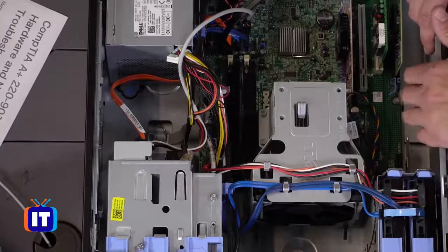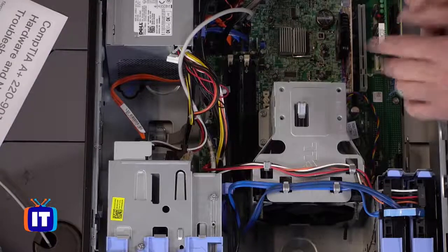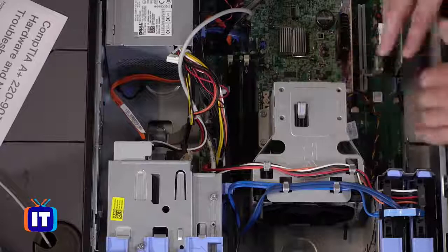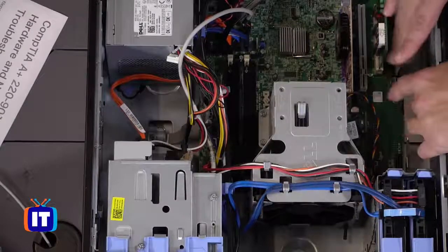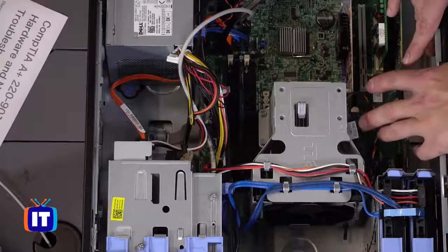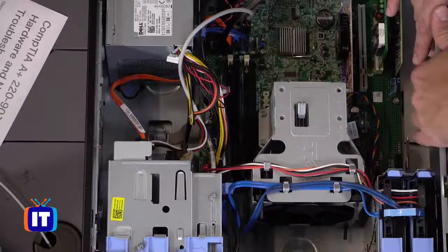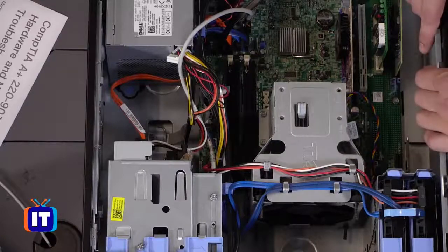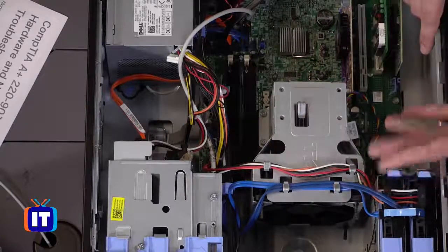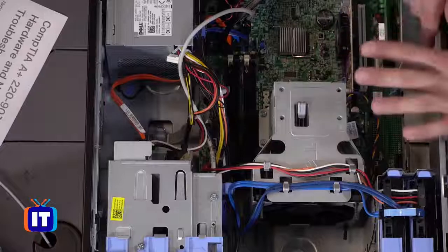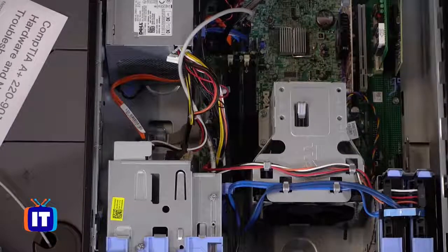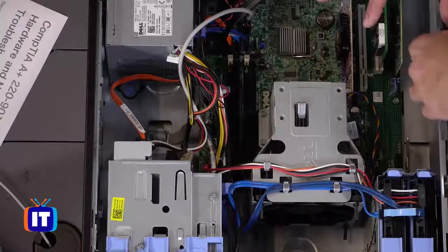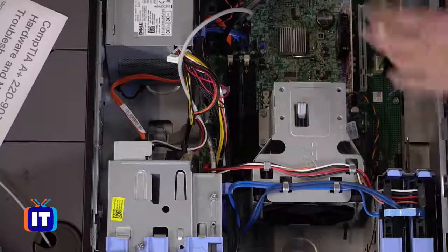And again, it lets me know that there isn't any residual power in here. Now, you might be asking yourself, Wes, where's your ESD wrist strap, right? Yes, memory, we realize memory is very, very sensitive to electrostatic discharge, but keep in mind, I am dissipating any electrical current in my body to the case right here just by touching the inside of the case. And both Dan and I are actually standing on electrically resistive mats, which is a commonality when you have some kind of tech bench. Sometimes you'll see the mats are actually on the bench itself, and they have a little snap button that'll let you clip on the ESD wrist strap right to the mat itself. I kind of find those a little bit restrictive.